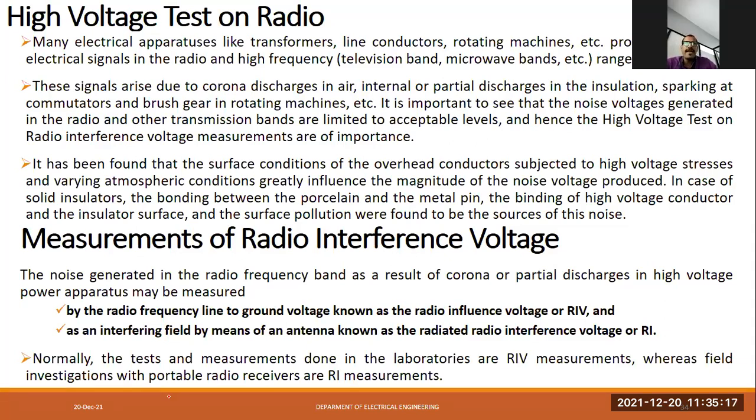So let us understand that whatever be the surface condition for the overhead conductors that are considered for high voltage stresses, the atmospheric conditions will vary from time to time, so they will have a great influence on the magnitude of noise voltage that is produced. Suppose there is a solid insulator having a bonding between porcelain and a metal pin,